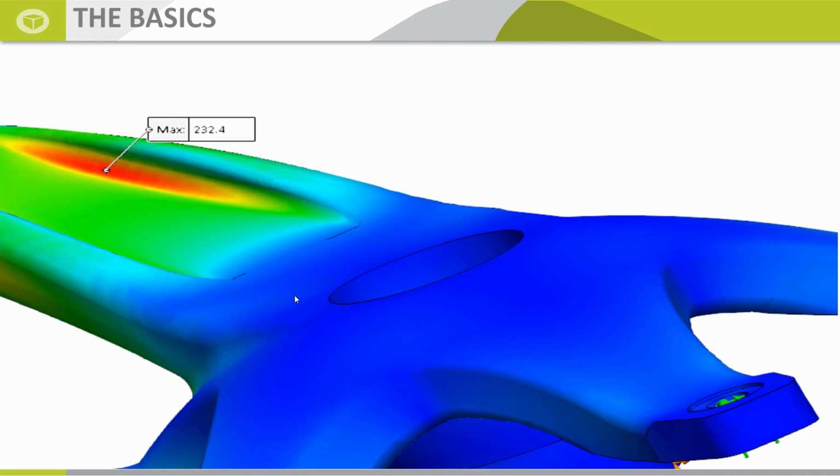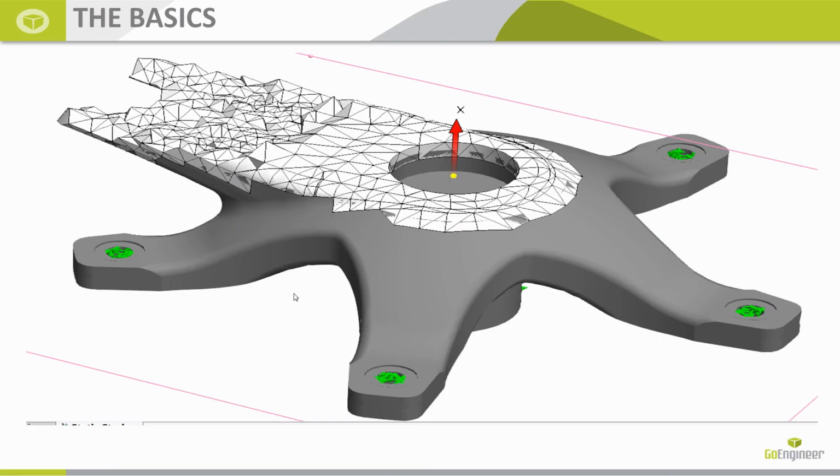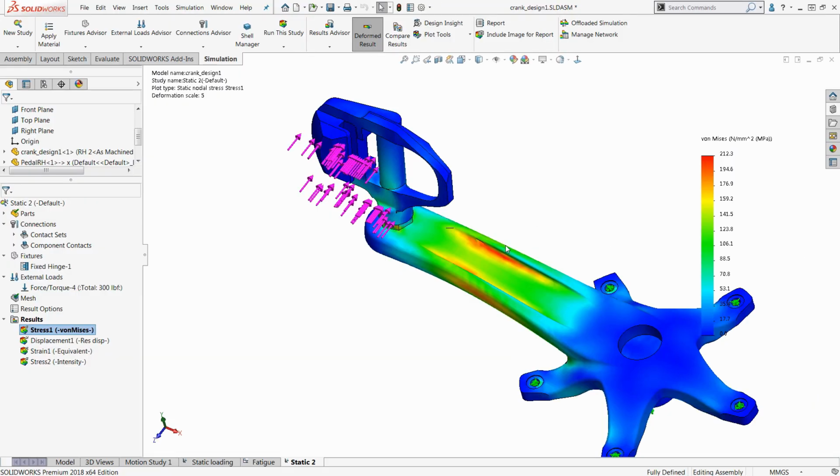Okay, let's go ahead and move on. The next is mesh sectioning. For those who've done SOLIDWORKS and used simulation before, you typically want 3 elements of mesh across the thickness of your model. So how do you go ahead and actually check what the mesh density is on the inside?